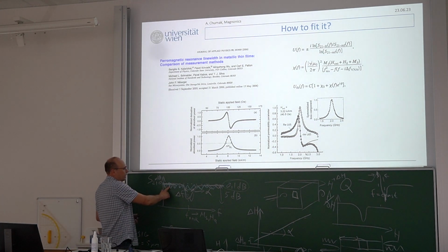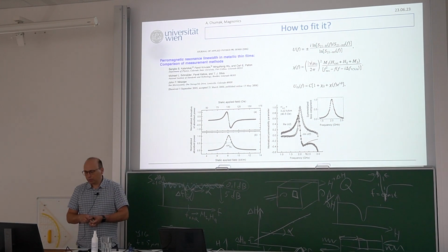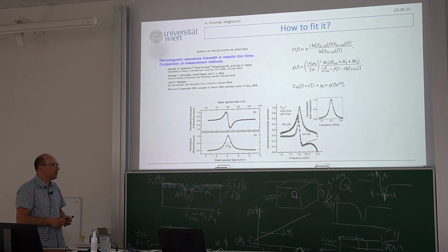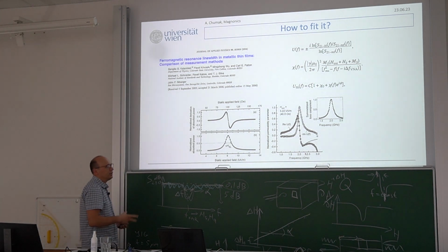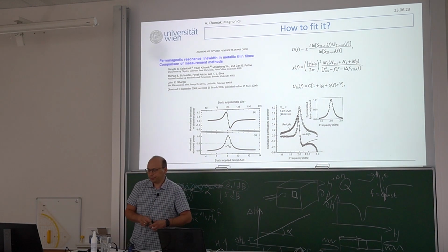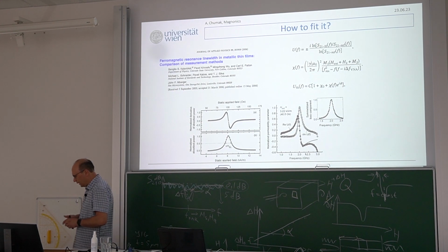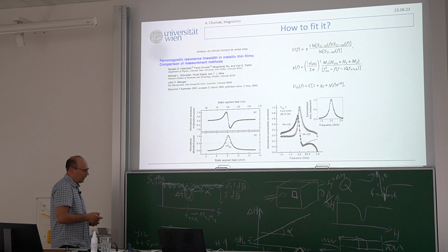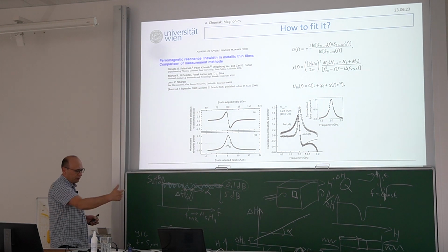How to take this reference signal? As I said, often people take zero field, but my recommendation would be to just detune the field slightly, because your YIG and GGG have a complex mu also, and it will change the electromagnetic properties of your strip lines.